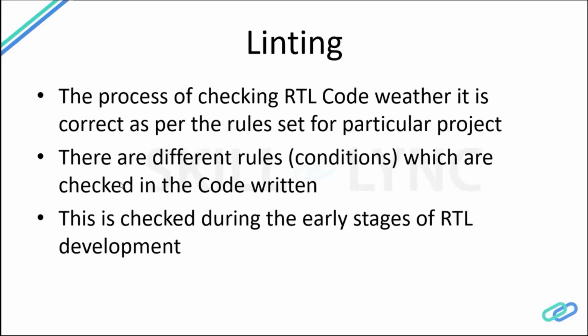This is done at the early stages of RTL development so that when we go to synthesis, we don't have to come back and make changes. Even in the synthesis step these checks are done, but we don't want to wait till that stage, where we go back, recheck everything and make changes, because most lint errors are small errors that we can avoid. Synthesis is done almost at the last stage of your design.